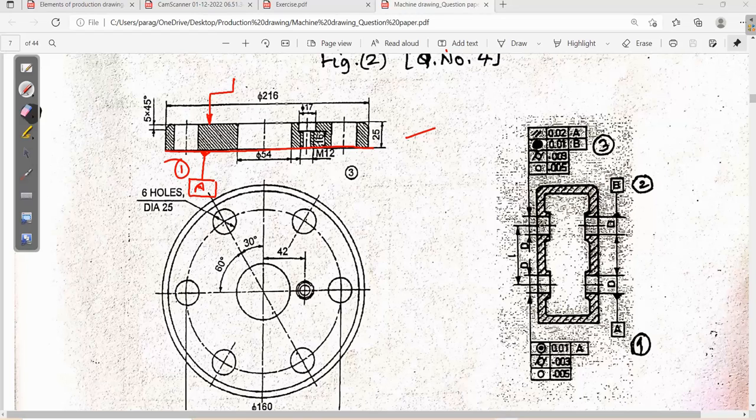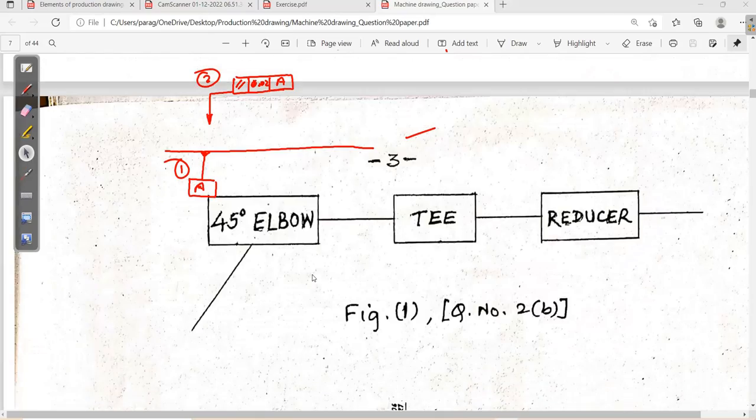Okay, now boxes you have to draw, 1, 2. In this case datum is required. So what is the symbol for parallelism? Just parallel lines you have to draw, then 0.02. Okay, the symbol you have to mention, and here we will mention the datum value. So this is 0.02 and the datum. Like this you should keep on solving this.